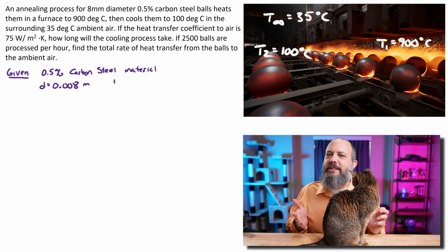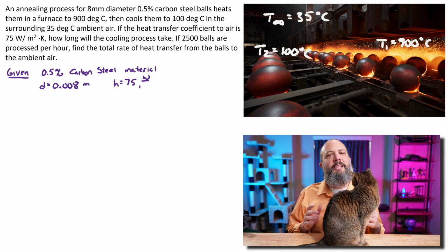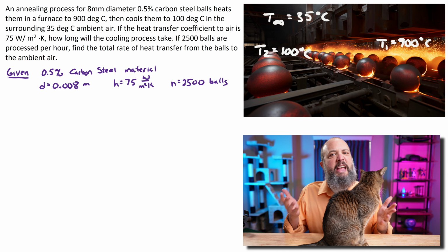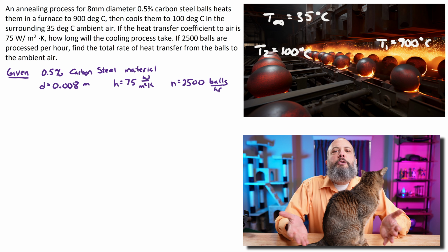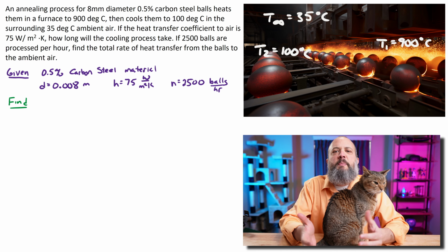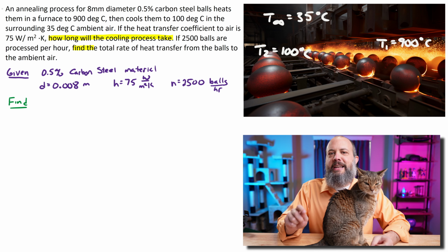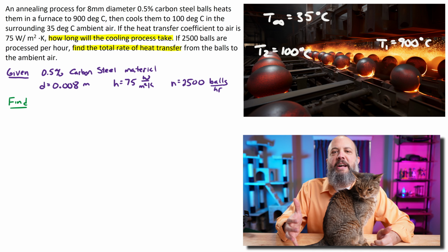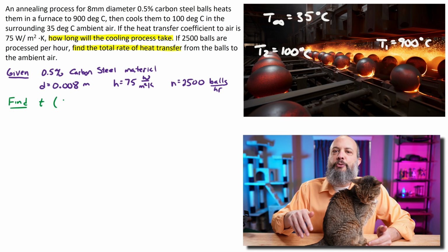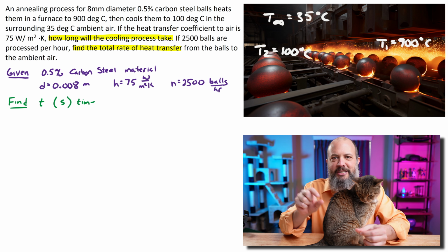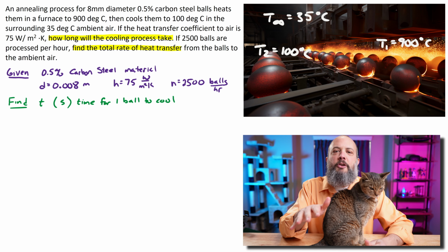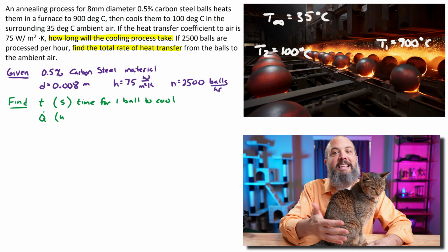So every mechanical engineer should understand basic terminology about manufacturing and metalworking processes, things like strain hardening. And annealing is one of those terms. So the purpose of annealing is to make metal more pliable, easier to work with. And so annealing is done by heating up a metal to a very high temperature above its recrystallization temperature. So when you heat up metal, the atoms themselves actually realign. And what this will do is make your material more ductile, less brittle.